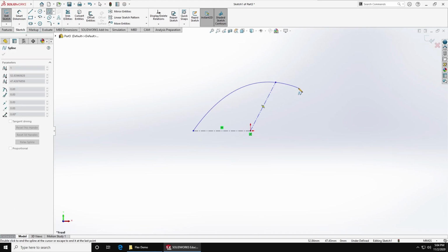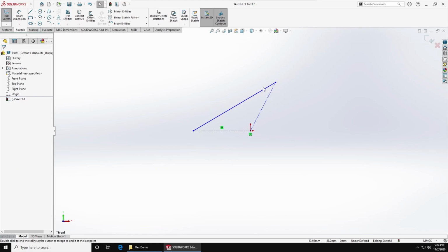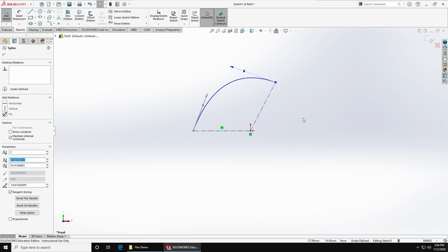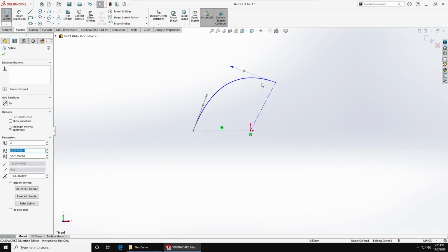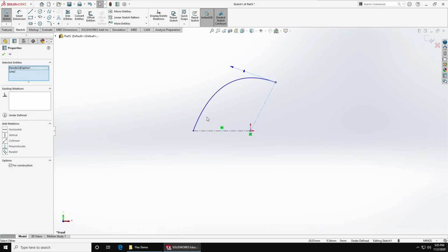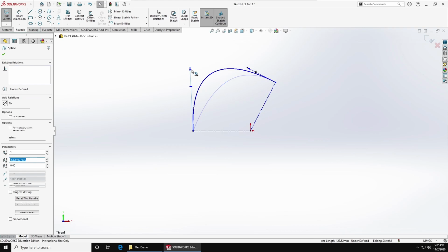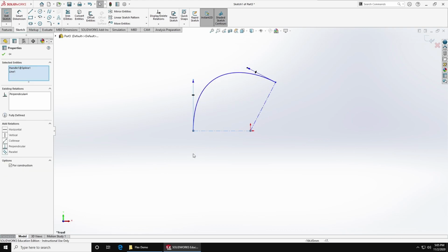that one. You can hit the Escape key to stop the spline, and when we left click on it, we can see that we now have these control handles. You can set the handle so that it is perpendicular with the construction lines that we created earlier, and we'll repeat the process on the other side as well. And this is going to ensure that the cable will always come straight out of the hinges.